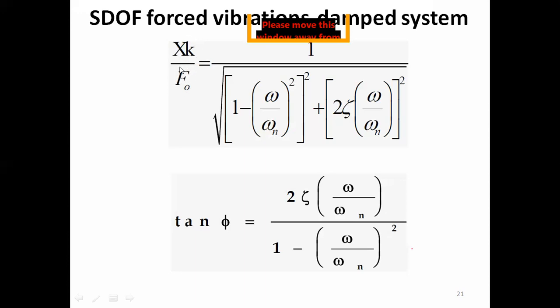So it would have the unit of force. And here again we have the amplitude of the force. It has the unit of the force. So it is actually the ratio of the forces here, so again it has no unit. So this side is unitless and also this side is unitless. So we come up with a dimensionless equation. This is a dimensionless equation. This is actually known as the magnification. This is the frequency ratio and this is the damping ratio.